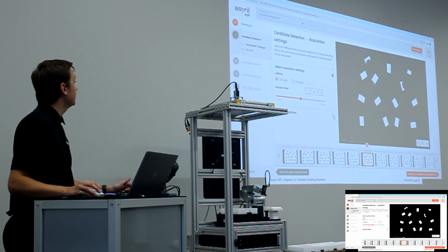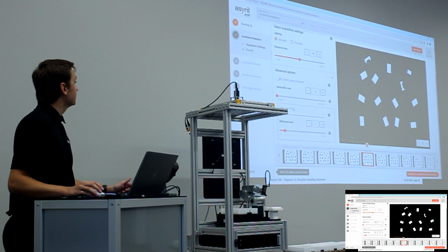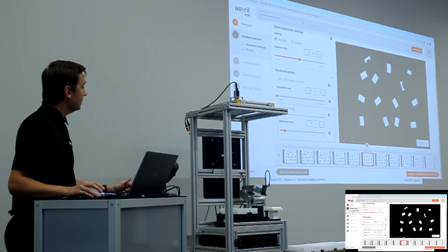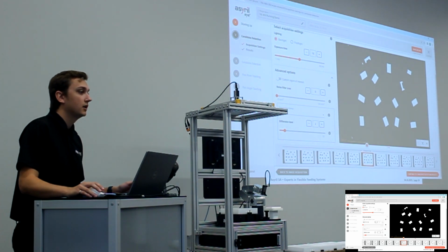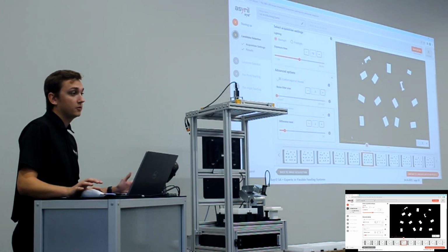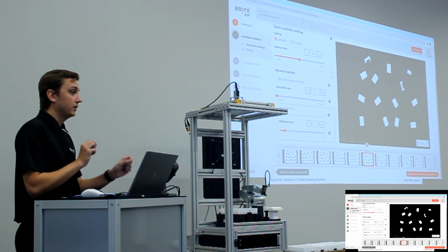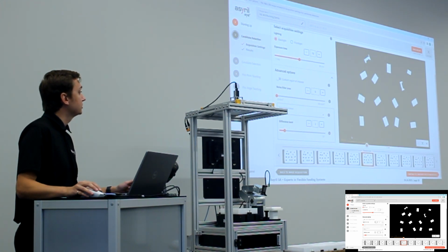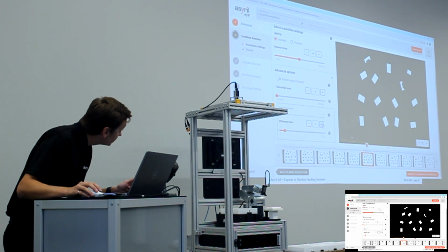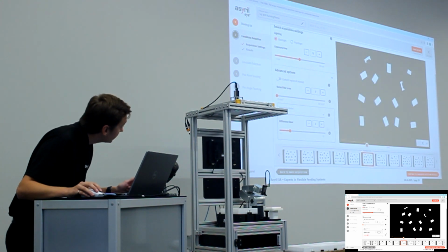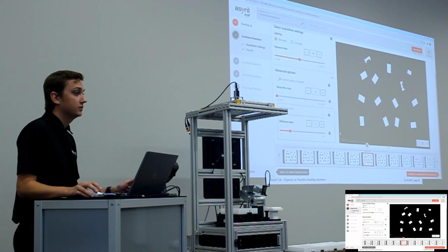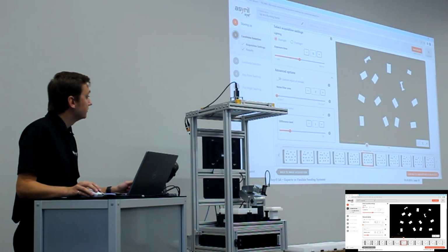And so in the advanced options, we've got our segmentation method here. Essentially what this does is it looks at the pixels around all of the other pixels. So it'll go through and look at the difference between the surrounding pixels, and that's how it's going to determine a part. So if we increase this difference level here, it'll essentially increase that threshold that we're looking for